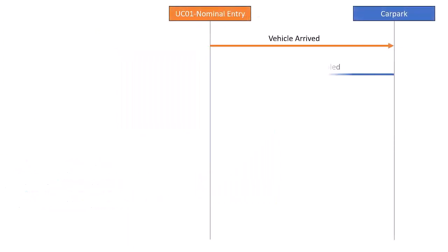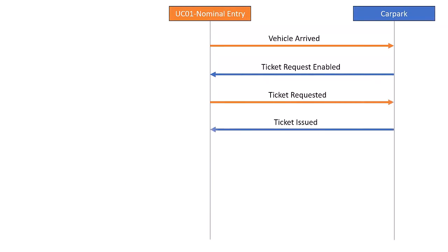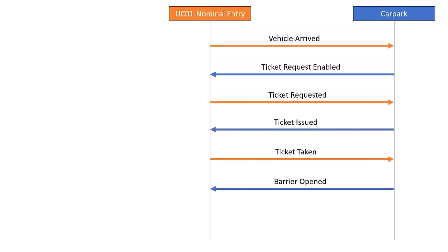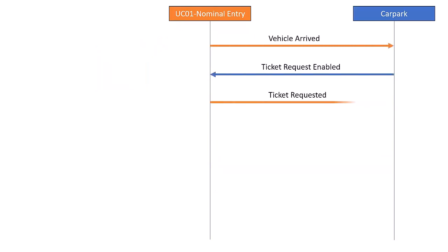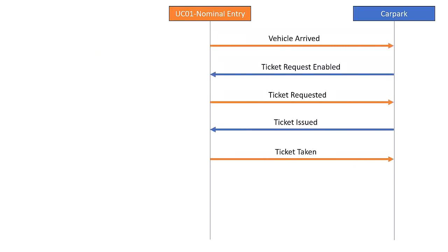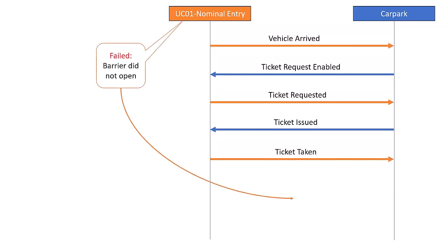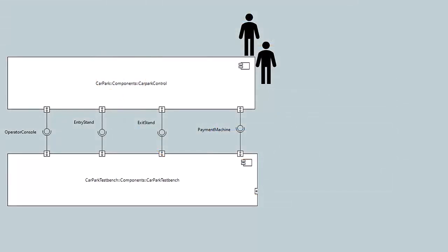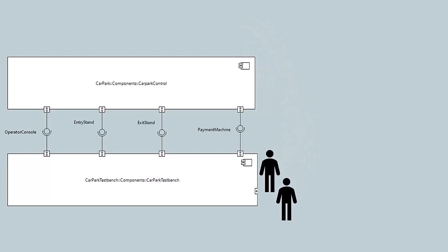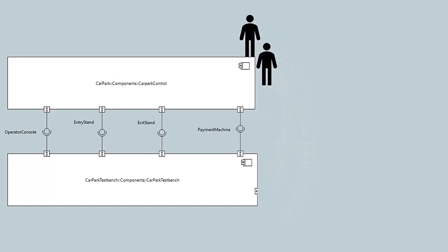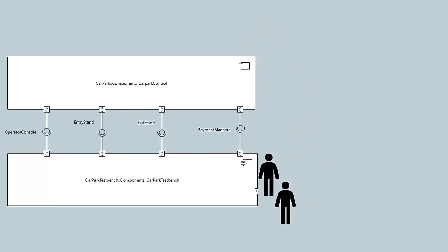We typically build the test bench and the test suite incrementally, along with the application models. When we have enough of the application modeled to support an interesting use case or three, then we build enough test bench and enough test cases to illustrate those use cases. We test and debug the application models that are supporting those first few initial use cases, and at the same time we're testing the newly developed test bench and the test cases.